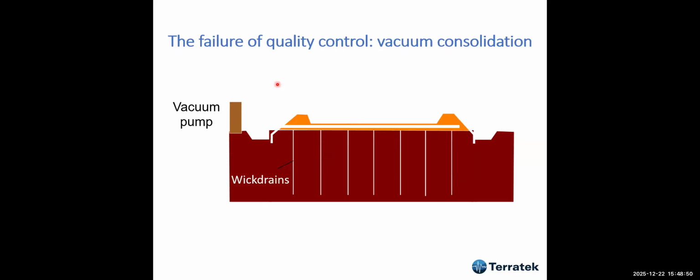It was a residential project in South Place, and the contractor asked me what I thought about that. I told them, do not do this without a trial bank. I know that it works in many countries. Vacuum consolidation works, but you have to maintain the vacuum. You have to take care of any leak, or it may not work. There are many possibilities of this